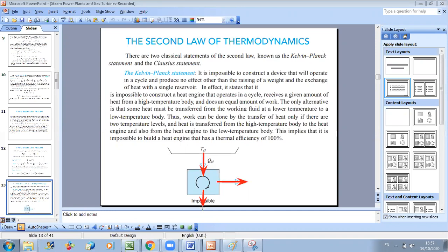Now, what do we do to increase the efficiency? To increase the efficiency of a heat engine system, we try to benefit from the heat we lose here. We are losing a certain amount of heat, and we try to use it back. If we use back the heat that we lost, we can save energy. One idea is to have a heat exchanger, because once heat is lost, I can take it through a heat exchanger. It can heat, for example, a fluid, and this fluid will heat my system. So I can restore a certain amount of the energy lost.